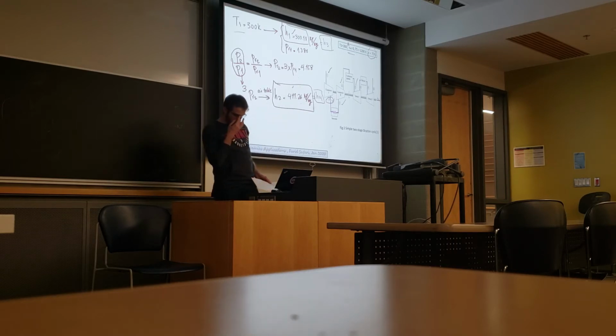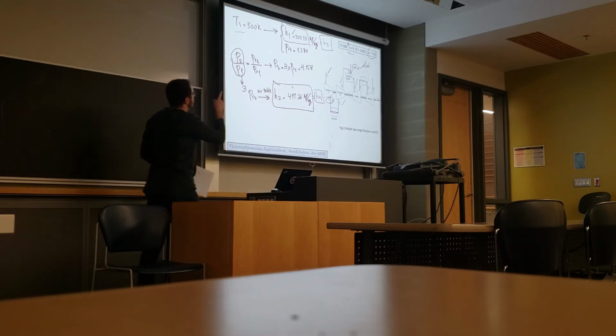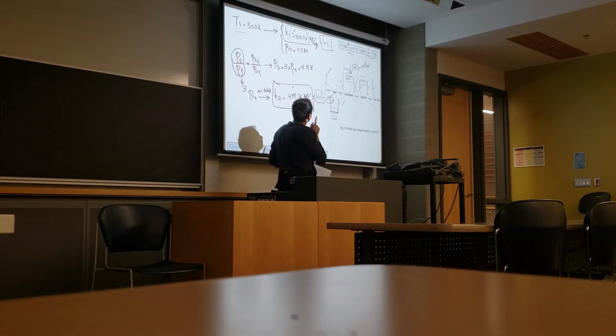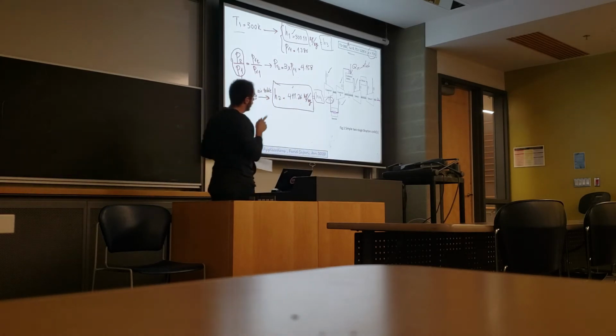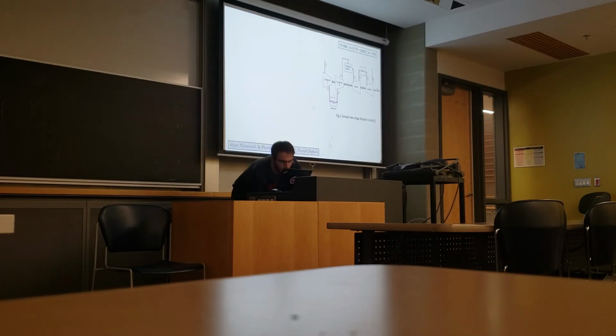So we have H1 to 4, and from 4 to 5 we have the combustion chamber where Qin comes from fuel. The fuel is burned there and gives some heat to the air, and it combusts with the air, and the exhaust gases are at high temperature and high pressure. So we have the Qin there. For 5 we have the temperature of 1200 Kelvin. So let's go to 5 and we can write T5 1200, and we have H5 again and PR5.